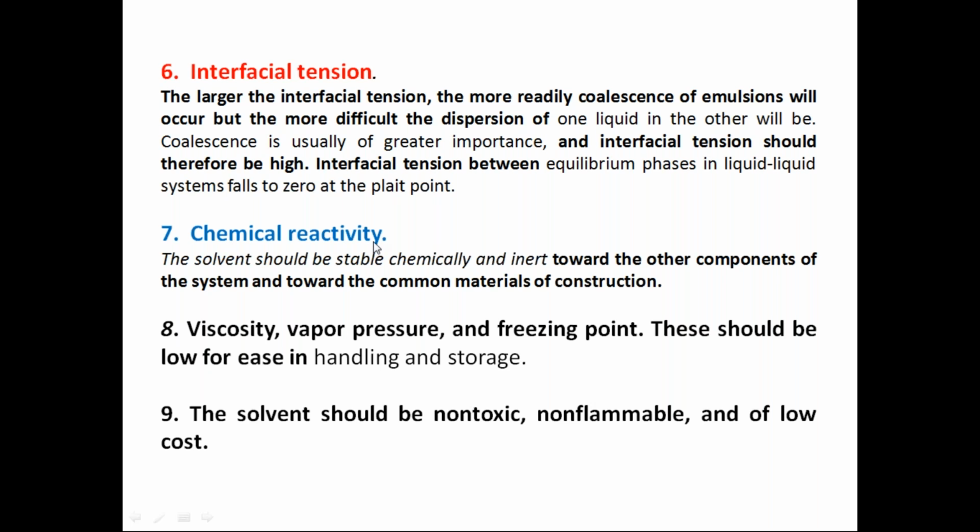Then the chemical reactivity. The solvent should be chemically stable, meaning whatever organic solvent you are adding should be stable. It should not react with either A or C, that is, the feed solvent or the solute. So the solvent should be chemically stable and inert toward the other components of the system and toward the common materials of construction.